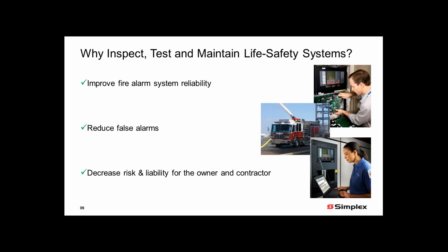And with proper maintenance, one of the other things that we try to combat in the industry is to reduce false alarms, or what we call in NFPA 72 nuisance alarms or unwanted alarms. As smoke detectors, for example, get dirty, it might take less and less smoke to activate them, and they could potentially cause a nuisance alarm for us. So with good maintenance and servicing of our systems in conjunction with testing, we can help to reduce those nuisance alarms.